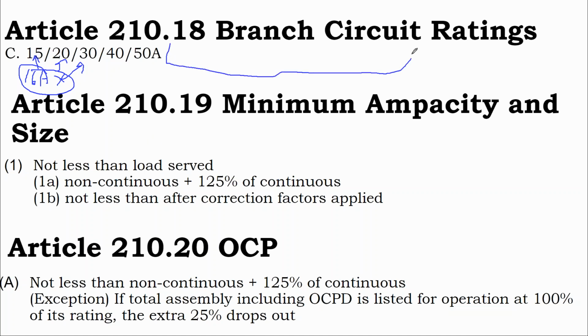When these options start spacing out and you start getting into larger and larger circuits, you may actually take the load and take your cable size and have the breaker be somewhere in between, so that the load interrupts before. So that the load that is possible to go through that cable cannot possibly exceed the ampacity of the cable. At any rate, we're going to start developing how to size a cable for a load.